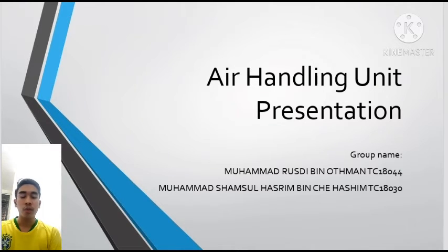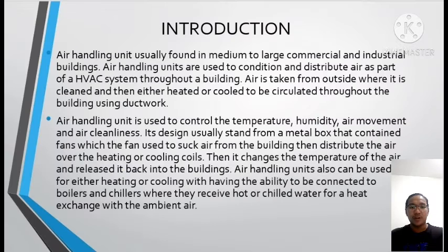So today I'm going to present about the air handling unit. Air handling units are usually found in medium to large commercial and industrial buildings. They are used to condition and distribute air as part of the HVAC system throughout a building. Air is taken from outside, where it is cleaned and then either heated or cooled to be circulated throughout the building using ductwork. An air handling unit is used to control the temperature, humidity, air movement and air cleanliness, and its